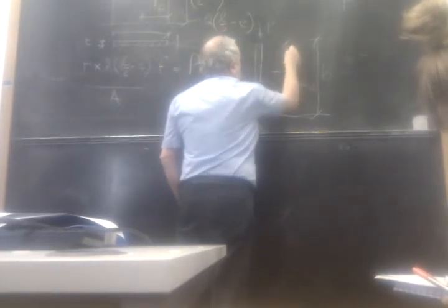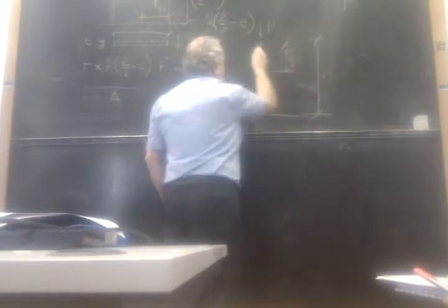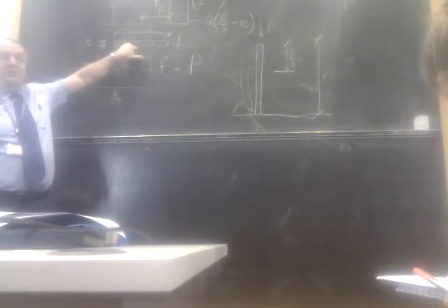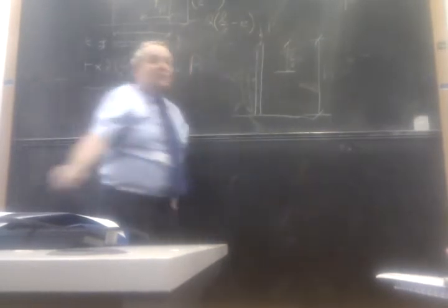But in a wall, you normally check it in two places. At the top and at the middle fifth, for that sort of situation. So if we do this up here, we've sorted out what happens under the slab. But you should really check that one there. If you do that, there are those formulae that we give you for eccentricity mid-height and how that's affected by slenderness. As far as this wall's concerned, that load is coming down the middle.